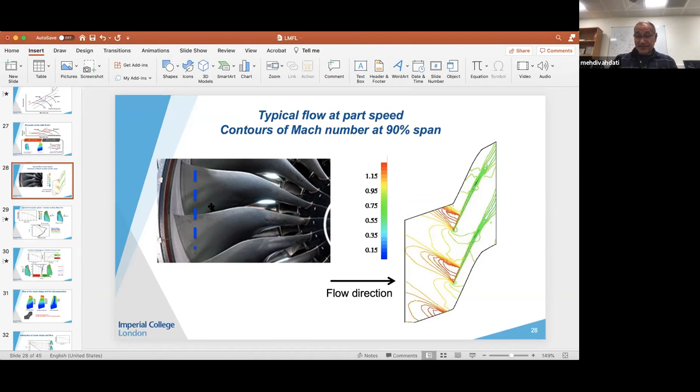The other thing that becomes quite important is that the blades do not vibrate in phase. They all vibrate out of phase. So when this blade is doing something, the incidence that it creates on the trailing blade could change. So all the blades at a given time do not see the same incidence due to the vibration, not only due to the motion of the blade itself, because that is going to be different, but also because the vibration of this blade feeds into its trailing blade.